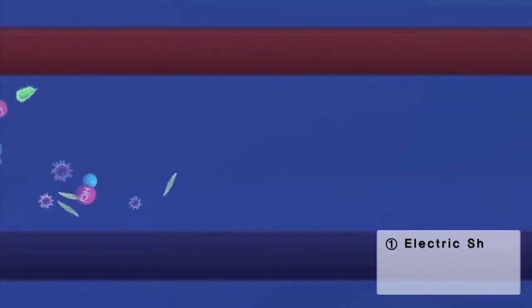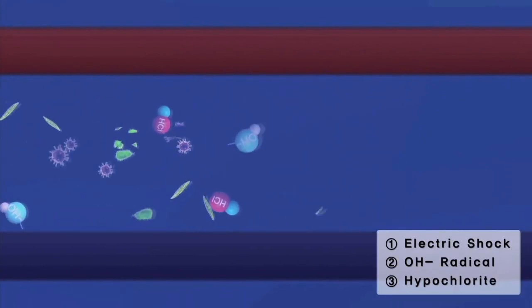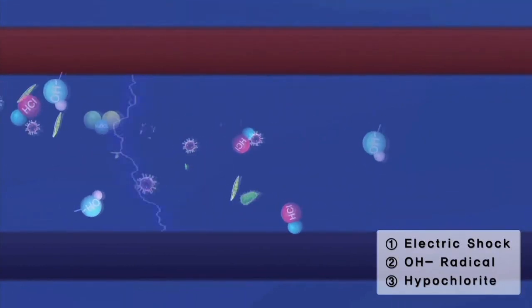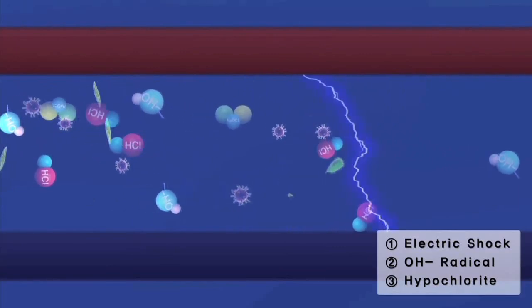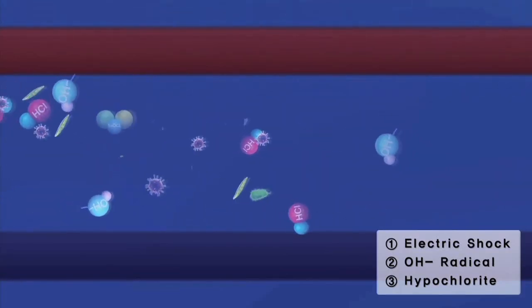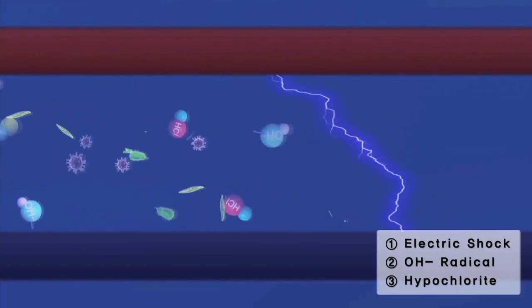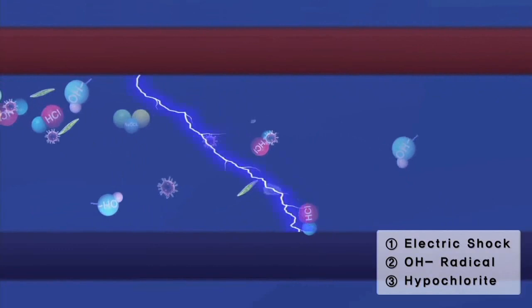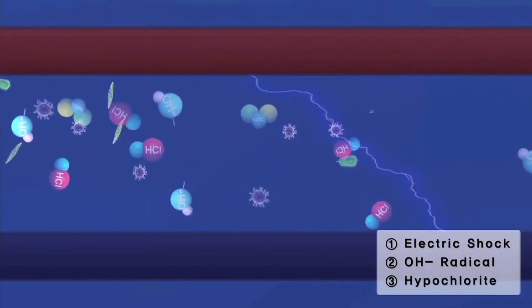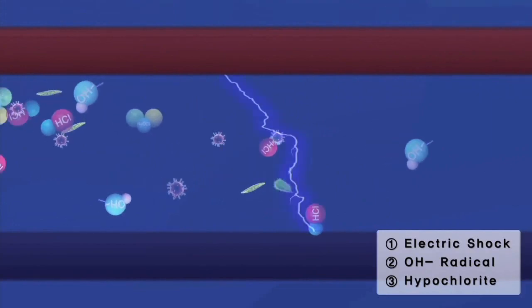1. Physical destruction of microorganisms by electric shock. 2. Oxidation by short-lived free radicals, hydroxyl radicals. 3. In situ production of 6 to 8 ppm of hypochlorite in the electrochamber unit to completely disinfect organisms. ECS surpasses IMO D2 standards by single treatment during ballasting only, without filtration.